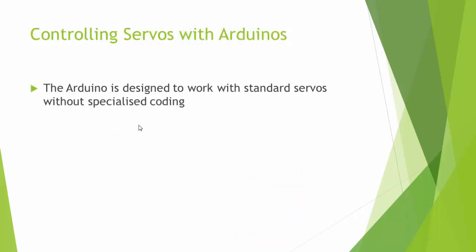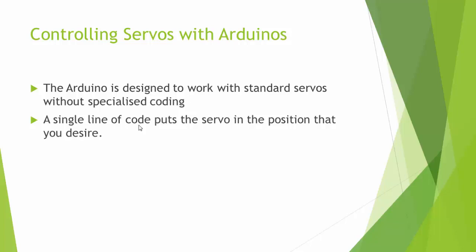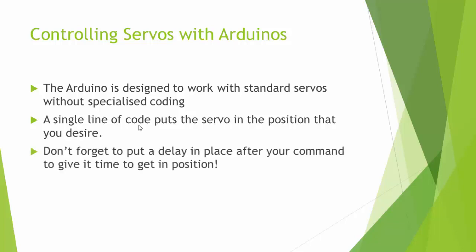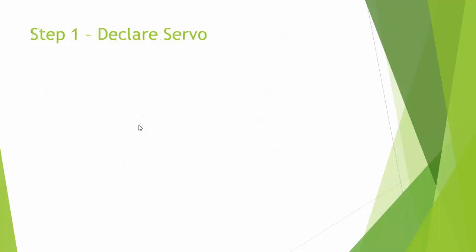So we can control servos with Arduinos. In fact, it's designed to work with standard servos without any specialized coding of any kind. And a single line of code will put the servo in the position that you want. Now the only trick here, and I'll emphasize this again in a second, is that you need to put a delay in place after your command. Otherwise the Arduino won't give it time to get where it needs to go.